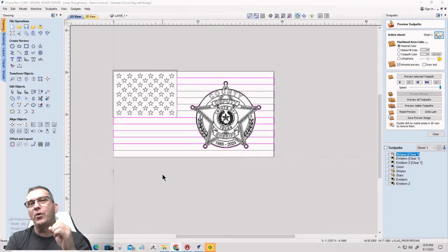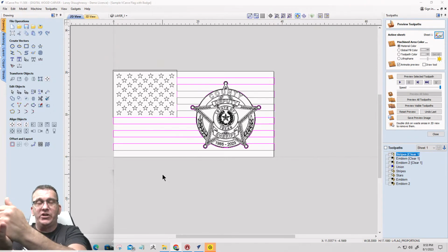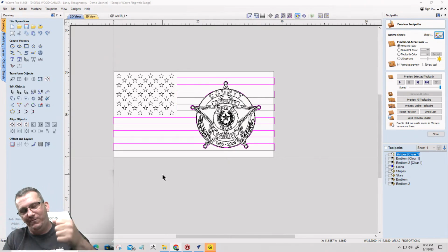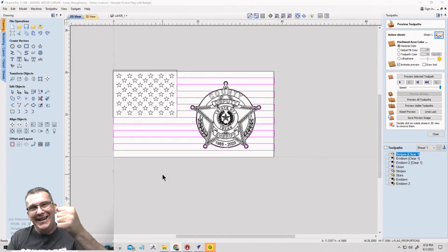if you are breaking bits, snapping bits, or pushing your material around off the clamps, you know, you have it clamped down but you're still pushing it off, or you're getting vibration and chatter and things like that. You can visibly see it, you can hear it.